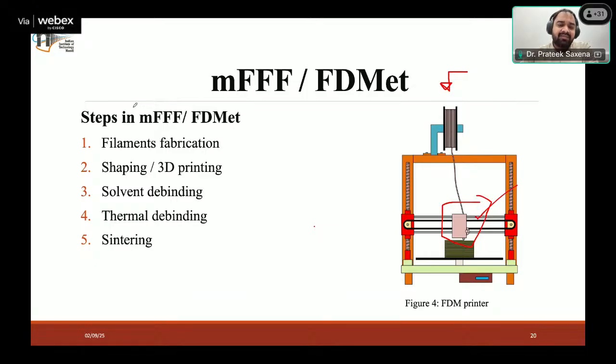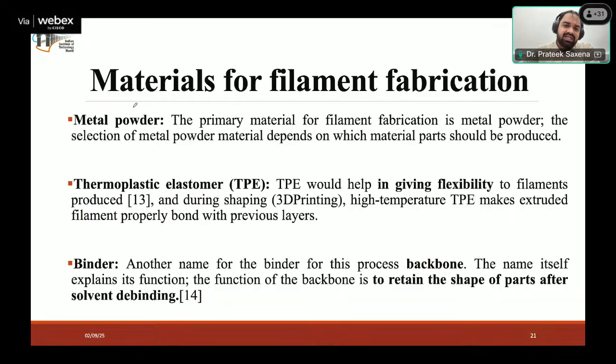Remember, I told you in the slide, in the first point, that you are not replacing all of the plastic with the metal powder. You are only replacing a fraction of that with fine metal particles. The remaining is still the polymer part, the remaining polymer granules, and then there are some other additives. So we can now talk in a little more detail about what exactly I would need when I am going to formulate my filament.